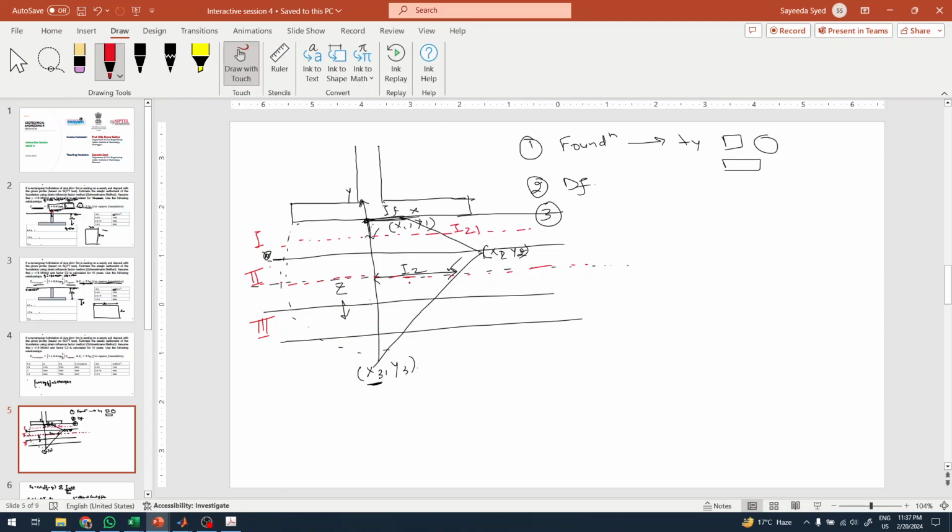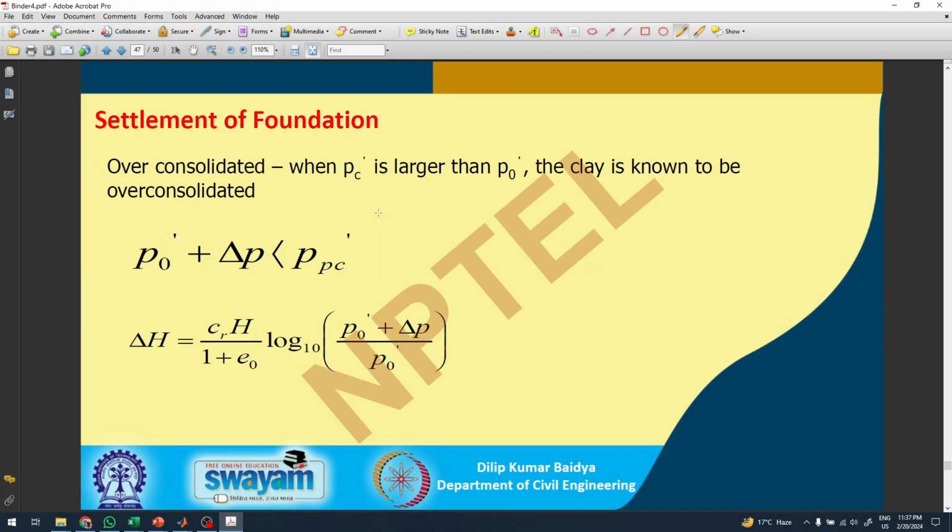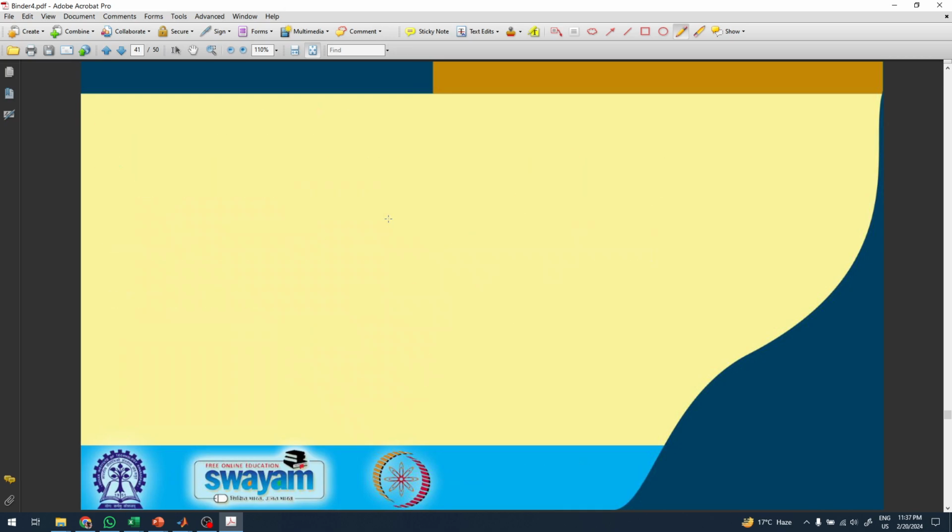This will be Iz1, this will be Iz2, and the center of this layer will be Iz3, up to this point, which has already been given by Schmertmann. In what case how much we will take will depend on the pre-existing values. Let us now check these values, for example, from the PPT itself.